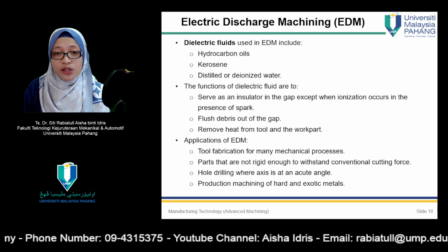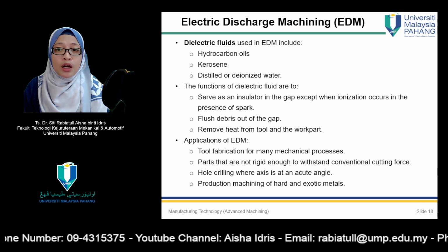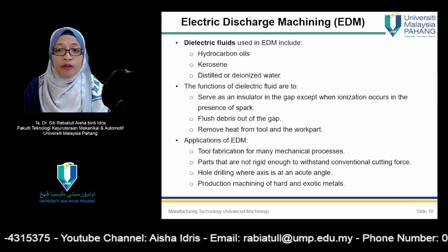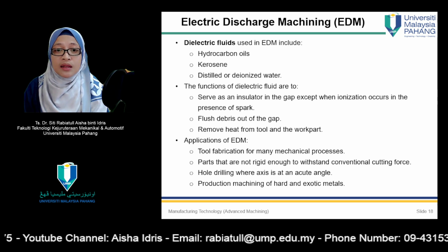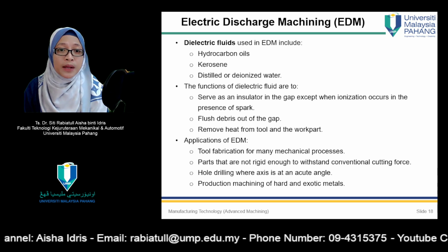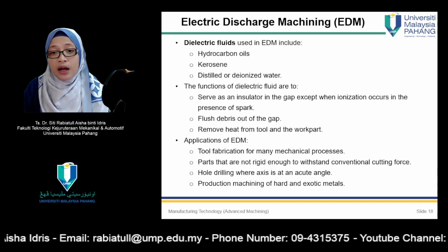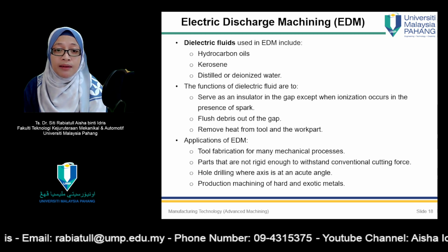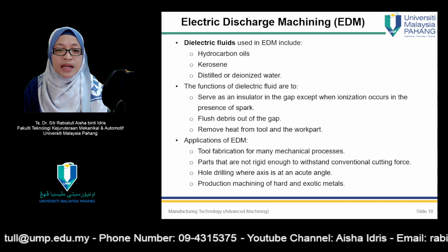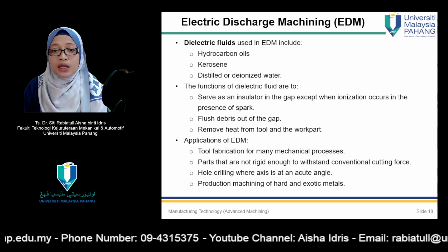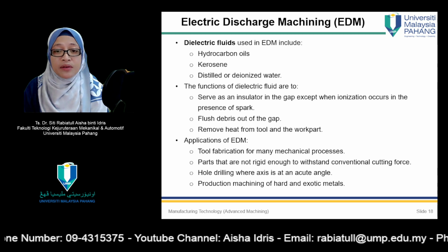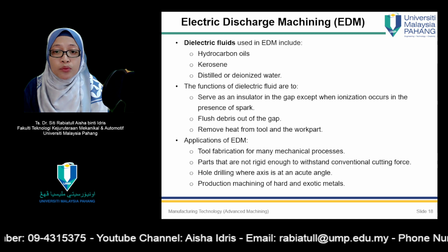Applications of electric discharge machining include both tool fabrication and parts production. The tools for many of the mechanical processes discussed in this topic are often made by EDM, including molds for plastic injection molding, extrusion dies, wire drawing dies, forging and heading dies, and sheet metal stamping dies. As in ECM, the term die sinking is used for operations in which a mold cavity is produced, and the EDM process itself is sometimes referred to as ram EDM.